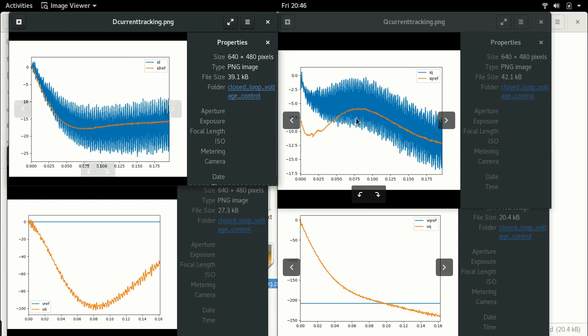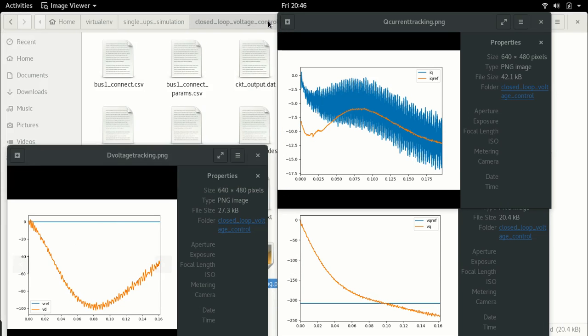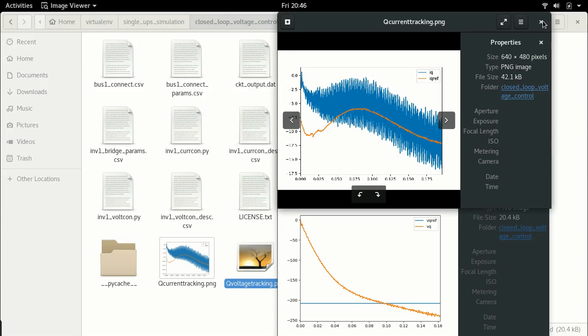And that's why you will see this is the amount of time it takes for the voltage to come close to the reference. Alright, and the same here. This is when it starts actually catching up. Here there's a pretty big error, and after that it starts catching up. The reason is simple, because of this error here in tracking. This error in tracking produces this delay, and because of this delay you have this coupled effect here. Even there is an error in the D voltage. So now that we progressed, at least we showed you these results.